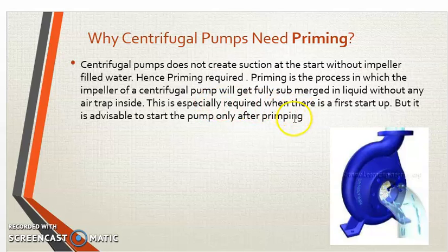This is especially required at first startup, but it is advisable to start the pump only after priming. It's a good practice in industry. Priming is used to fill the liquid into the full casing of the pump body, and we don't want any air bubbles or vapors in the casing, so as to prevent the pump from cavitation.